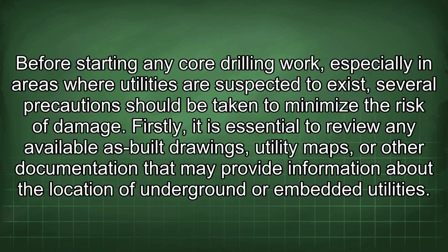Before starting any core drilling work, especially in areas where utilities are suspected to exist, several precautions should be taken to minimize the risk of damage. Firstly, it is essential to review any available as-built drawings, utility maps, or other documentation that may provide information about the location of underground or embedded utilities.